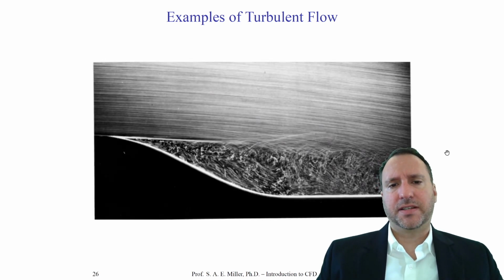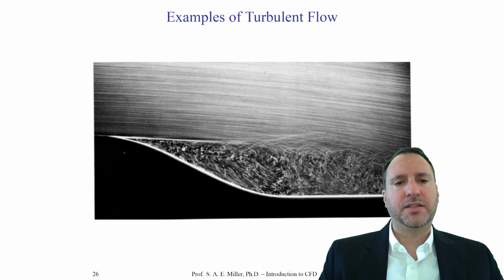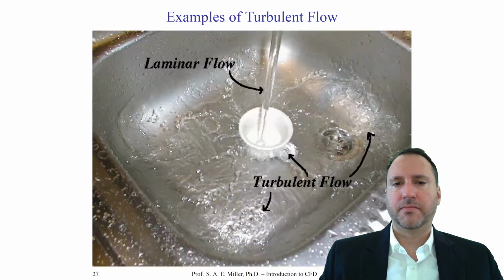Here's a backward-facing step. You can see this beauty of turbulence forming behind the step. Here the flow is laminar. Down near the step, backward-facing step, if you will. Actually, it's a hump, excuse me. The flow separates, and you see large turbulent structures forming here, shedding downstream.